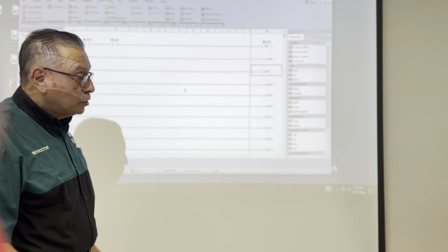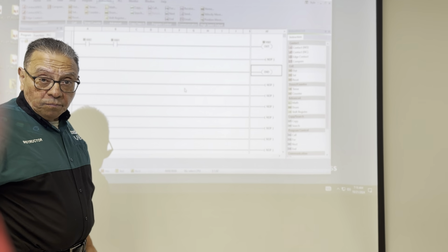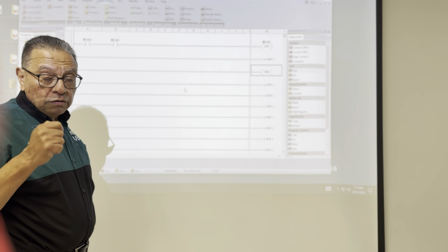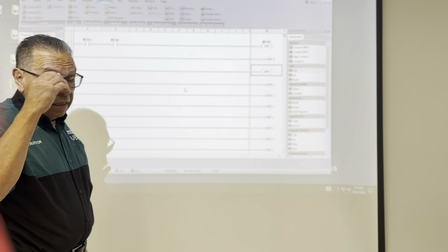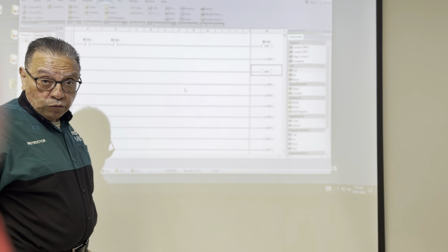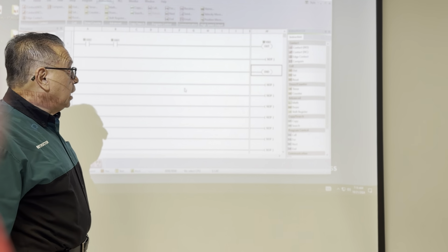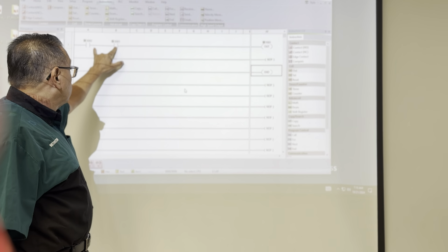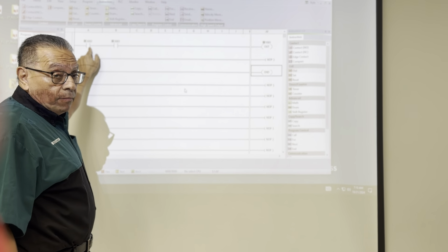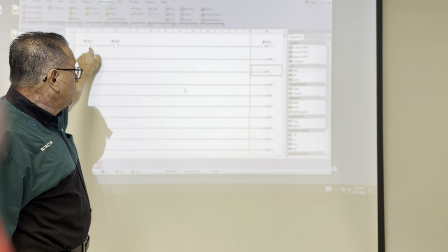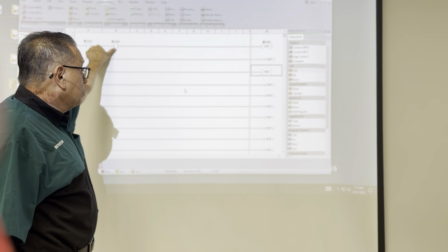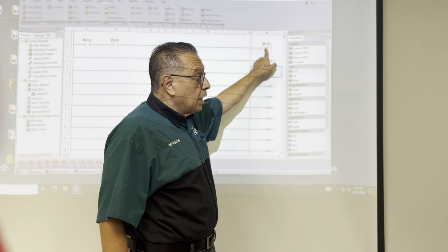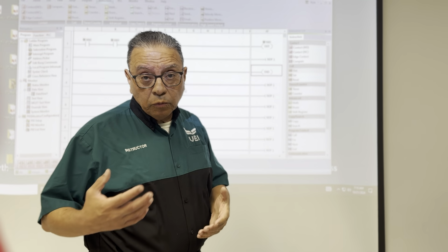In other words, if I am using the cooling system, the ambient temperature should be higher than 78, and there should be people in the room. So my motion sensor is closed, my thermostat is closed, both of them are closed, then I will have the output.